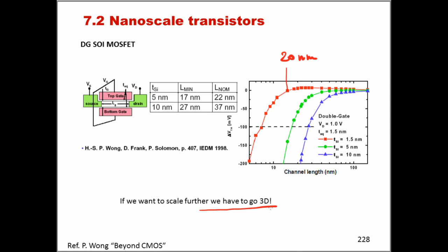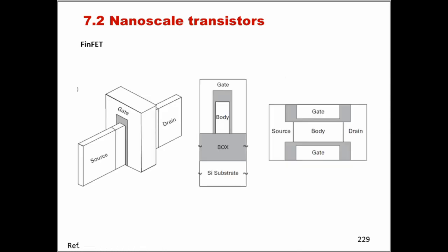So in all new devices that you buy today, if there is a MOSFET inside, it will be a 3D geometry, which we've said is either a FinFET or a gate all around. So here you can see the idea behind the FinFET. You have this piece of semiconductor that protrudes out of the plane of the substrate, and the gate is surrounding three sides of this fin.